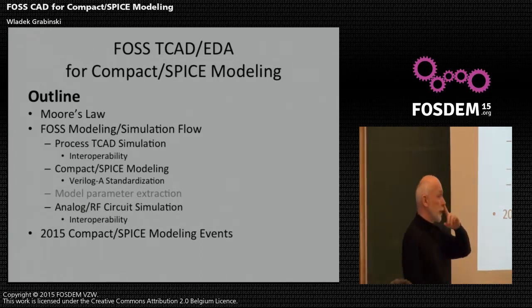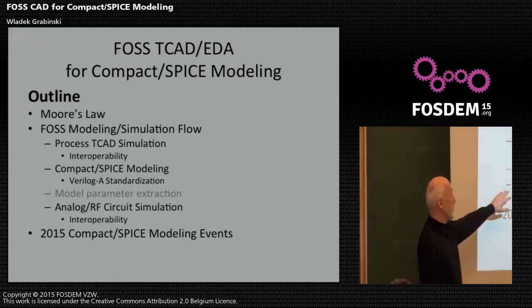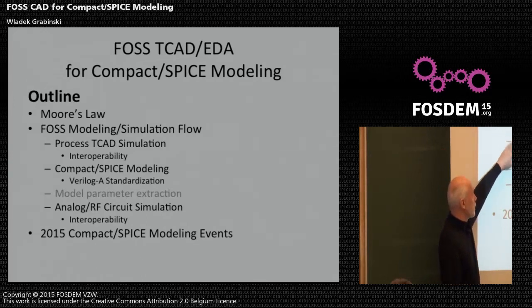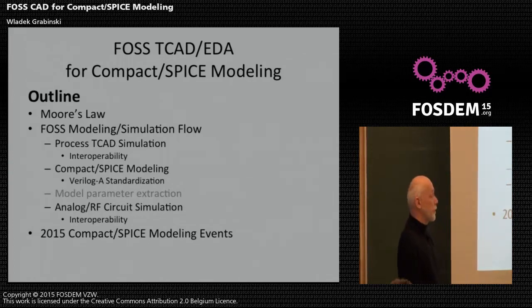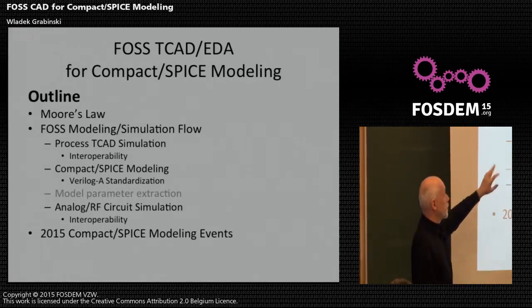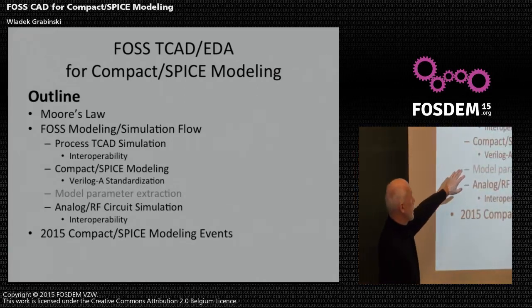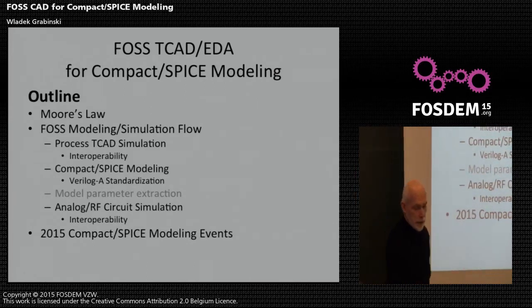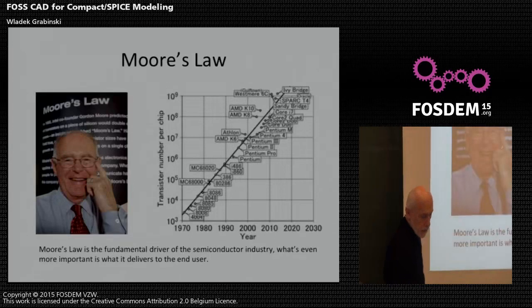There is an important part which we are not addressing today. It's parameter extraction and library generation to interact between models or technology models and analog simulation. And then there's reference to analog RF, mainly analog RF simulators, referring to both Qucs and ngspice, giving examples of other tools. On each point, I would like to raise an open question about interoperability, Verilog-A standardization, just to smooth out the communication, information exchange between different tools.